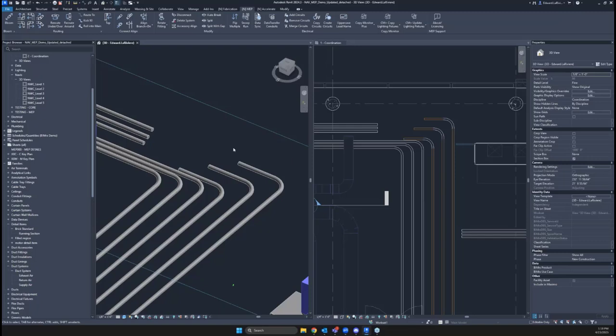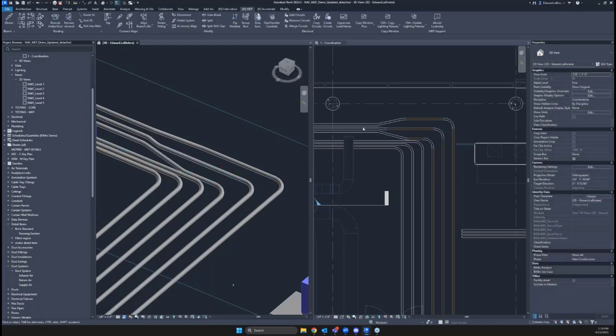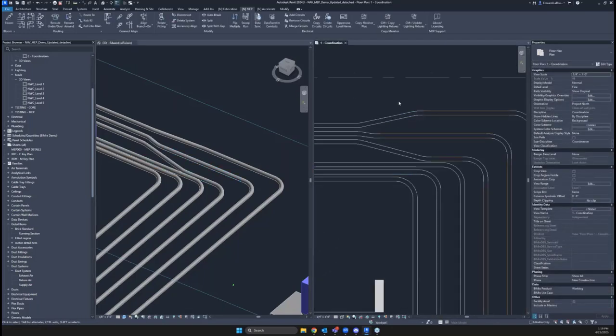You have to cut sections, rotate perfectly, probably not going to get the angle you want to get. It just stinks. So we're going to 1-button it. Route 2. What angle do I want? I can either choose it here, hit that drop down and pick it, but I'm thinking 15 degrees sounds good to me. Start, finish, start, finish, start, finish, and we have a perfect roll on each of those.